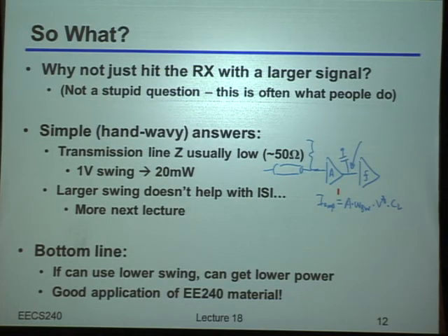Does this make sense to everybody? So again, the real key point here is that if you have a system where the impedance is very, very low, then getting a certain amount of voltage swing costs you a lot of power. Whereas if, for example, on the receiver, I can get much higher impedances, on the net, I can probably do much better by putting gain in the receiver than by just putting the maximum swing I can in the transmitter. Now, I'm describing this as a unidirectional trade-off.